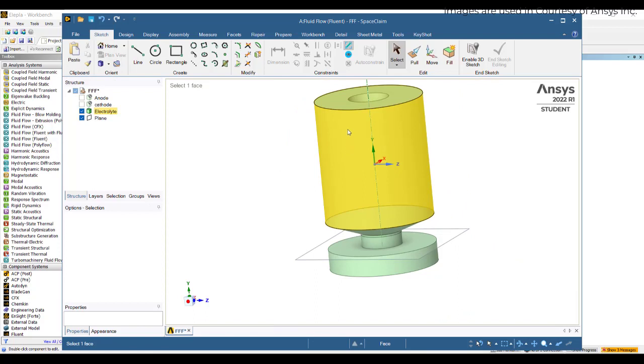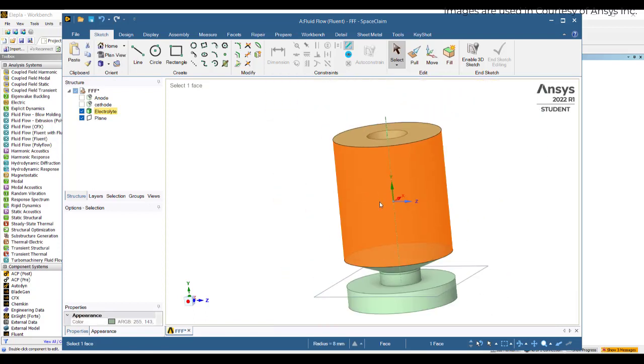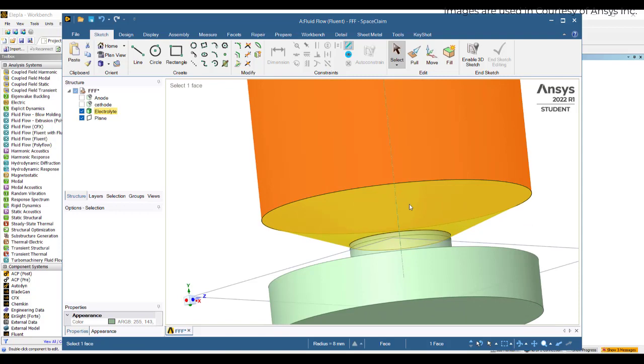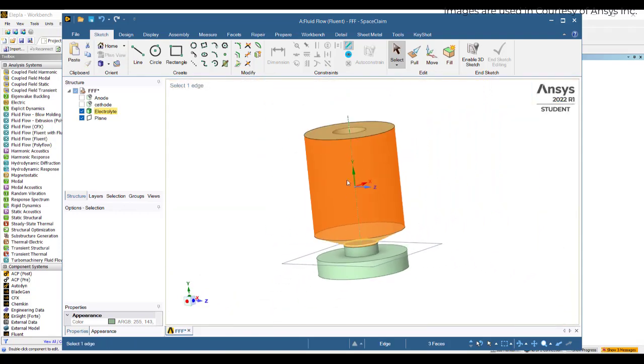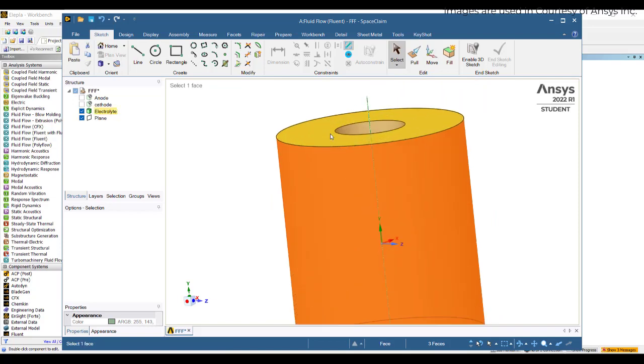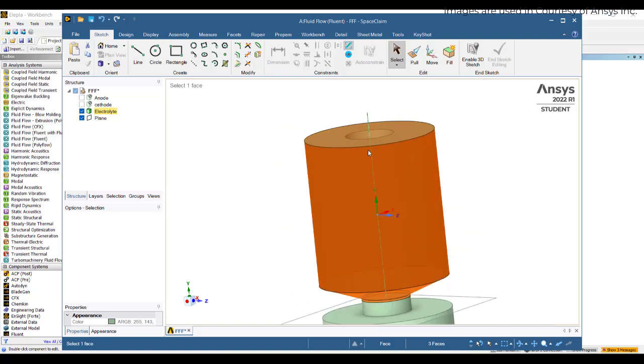So this will be our cathode wall, combined with these three surfaces, onto which the chromium alloy or chromium metal will be deposited. I'm taking potassium chromate or potassium dichromate solution. So Cr2O7 2- ions are present in the electrolyte solution. They will overcome the barrier of the Gibbs free energy and deposit onto the cathode, right?